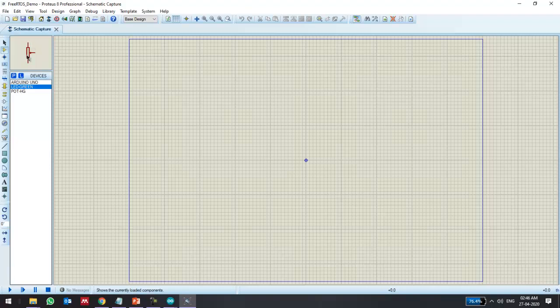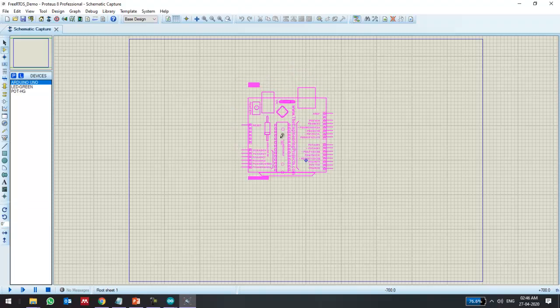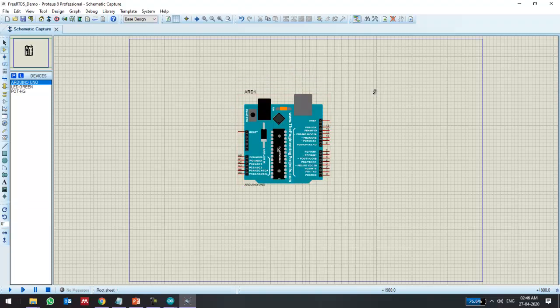First we get the Arduino UNO, click on this and then bring it to your schematic drawing area. Click once, and you'll get the Arduino UNO board. As you can see, it has all the external pins like a normal Arduino UNO board, but very importantly, the inbuilt LEDs are not present here. That is why we purposefully use pin number 13 to perform the blink operation.